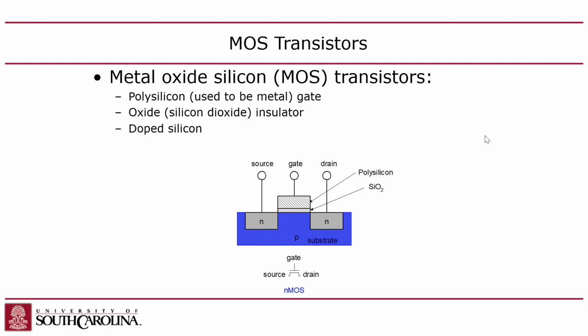The nice thing about silicon dioxide is that you can make it by basically taking the top of the chip surface and heating it up, and it makes silicon dioxide. You oxidize the top layer. You might say, well, why isn't the whole thing covered with that then? Well, you create a mask. You do this process called masking, right? So you can mask off this part, and then you heat the exposed part of the substrate, and you can naturally create that nice insulating layer just by cooking it, right?